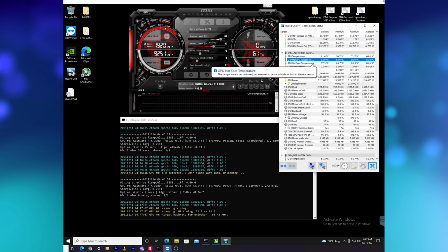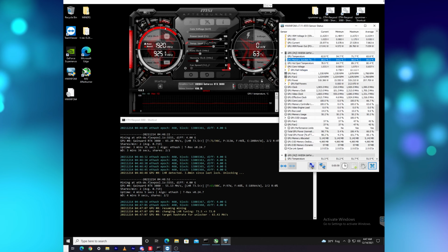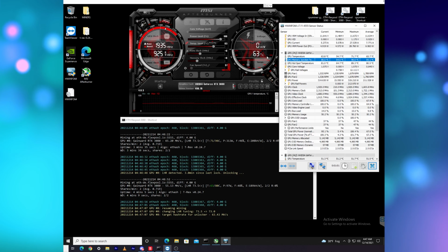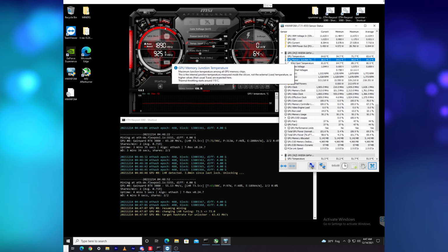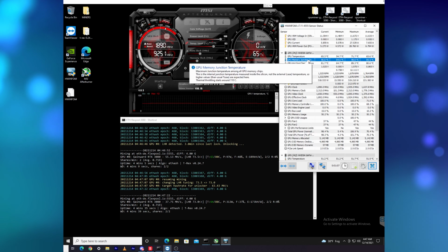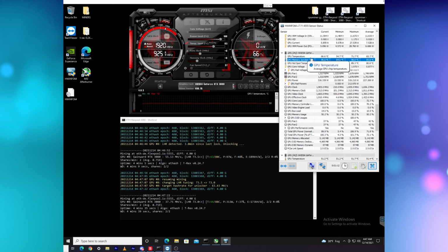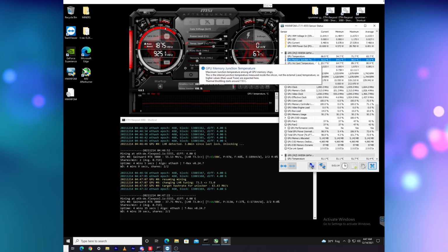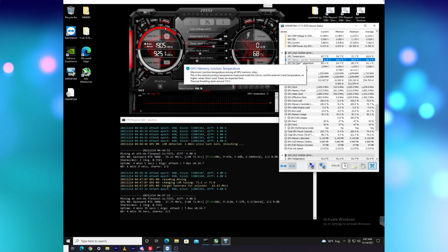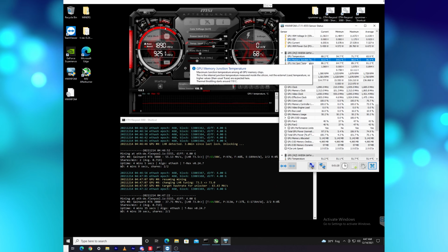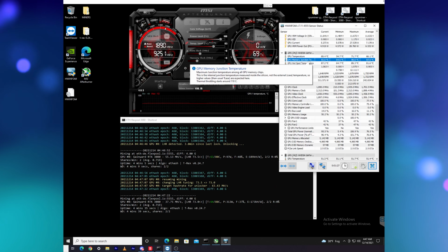At the moment, you do have to keep in mind one thing, which is actually very important. This fan speed right here that you are seeing on auto is directly synced with the GPU temperature. So the GPU temperature is the temperature of the die of the GPU. That's not the temperature of the memory junction. So that is quite important because you actually have to ramp up your fans quite a lot more in order to achieve better results on the memory temperatures than just leaving it on auto, which can basically, not overcook, but anyway, you get the idea, it's going to let the GPU junction temperatures go quite high, and that is definitely something that I'm not recommending.